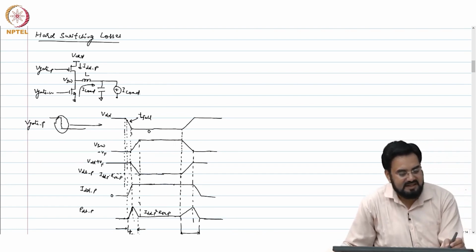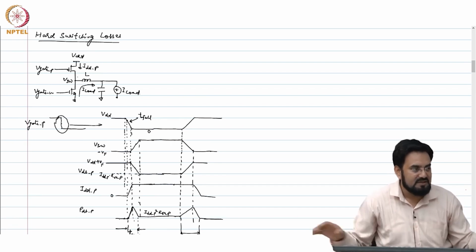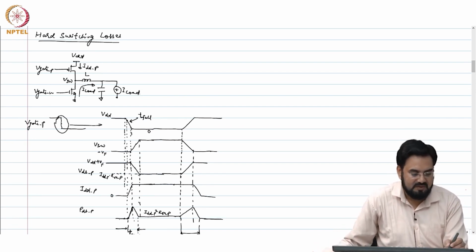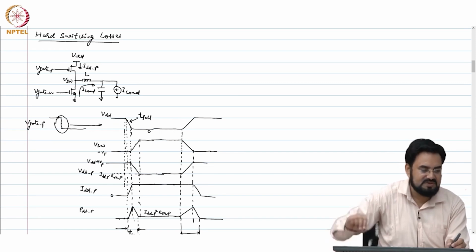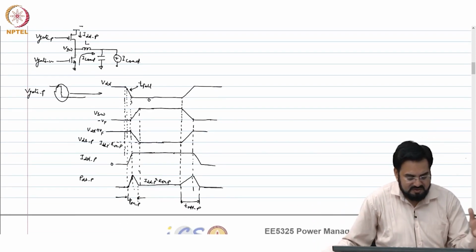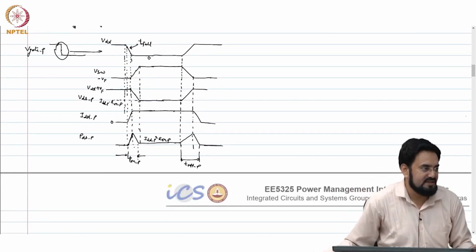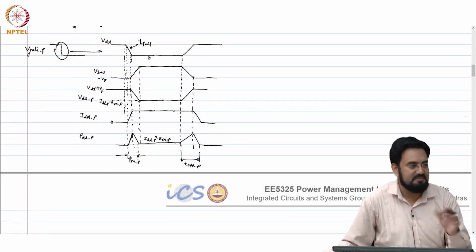And there are some parasitic caps on the VSW itself when you design. These are some routings, and usually this VSW is connected to the inductor externally. So, those pads will also have some capacitor. So, there will be some delays associated with that, but in the best case this is what you can achieve actually. In other cases it might be even worse.